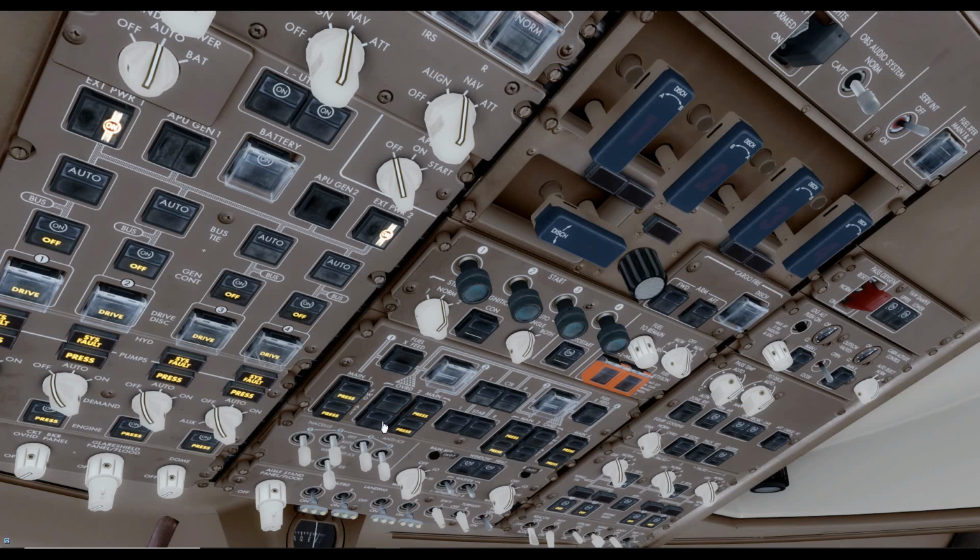Then coming down to the fuel, we need all crossfeeds to be on at this stage, and that's shown with the white piping light shown in each push button, and there are no valve lights shown in the cross-feed push buttons. All of the main tank pumps should be showing the amber pressure light because they're not online at this stage, and all of the pumps at this stage should be turned off.